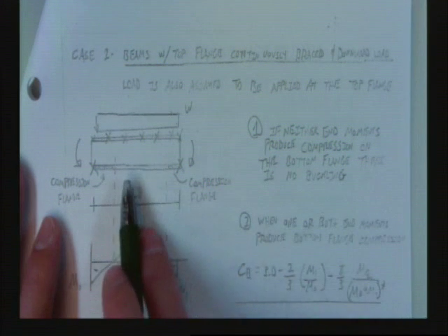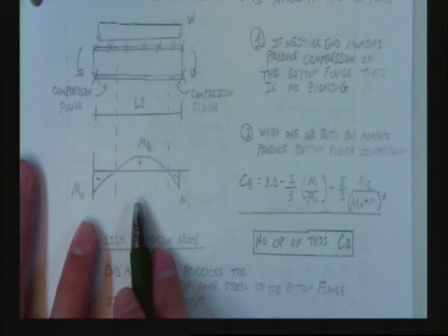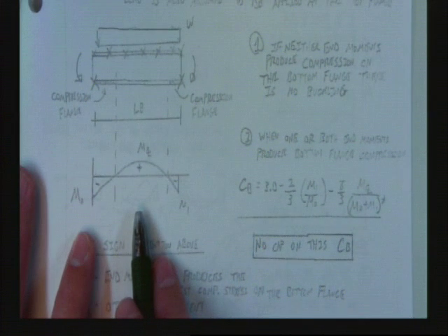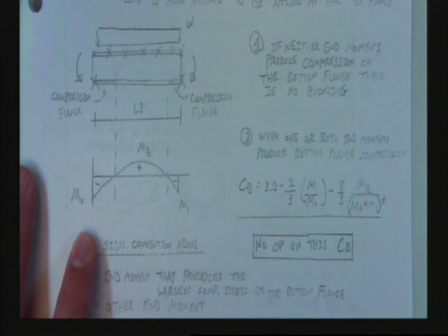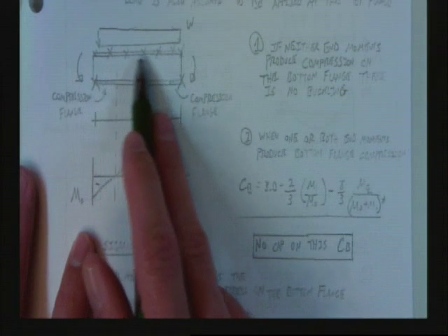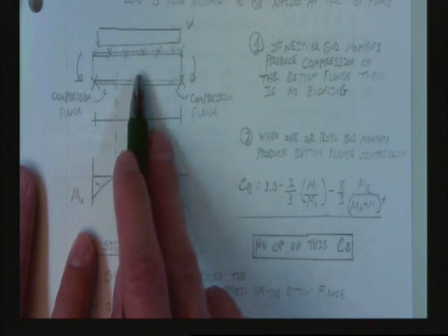Well, it's going to depend on what the moment diagram looks like, right? Let's say the moment diagram looks like this. What are you going to use for L sub B? The length of the beam. How come? Well, there's a brace here and a brace here on the top and bottom. There are braces here on the top. And did we say braces on the top were effective braces? That was the review today, right? Were braces on the top flange only effective braces?